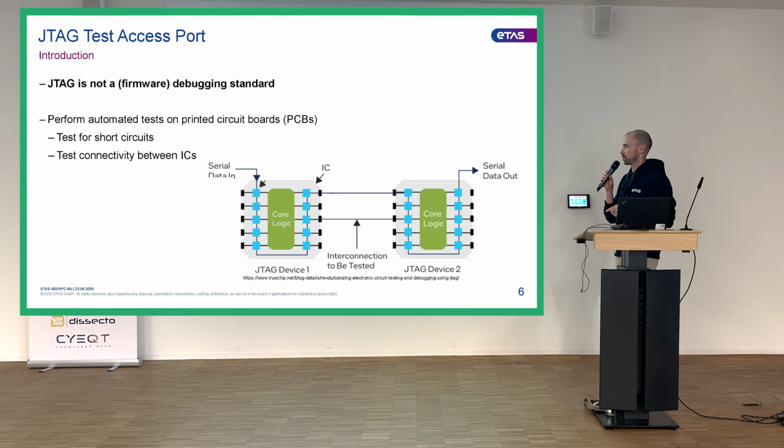Here we have two microcontrollers, and we have interconnections between them, and now we want to test them. Let's say we want to drive this pin here, and then we want to measure on this side. So we drive this one high, and then we measure here and see if the value is actually high as well.